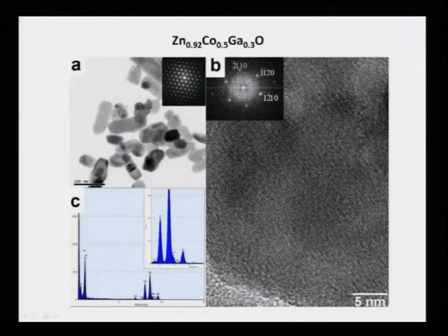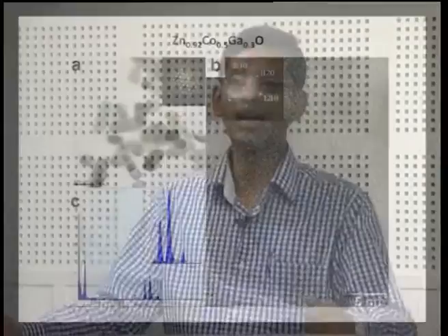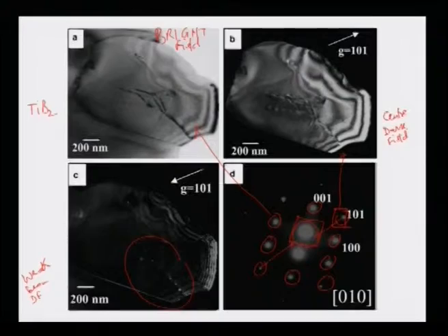This again is basically to describe how the electron microscope can be judiciously used to obtain a lot of information, particularly the spectroscopic and the real space information. As I said, a diffraction pattern can be used to generate bright field, dark field, weak beam dark field, and center dark field images. The diffraction pattern basically tells you the reciprocal space information, as we have already learned in the normal course on characterization techniques. So, the spots are actually related to the reciprocal space.